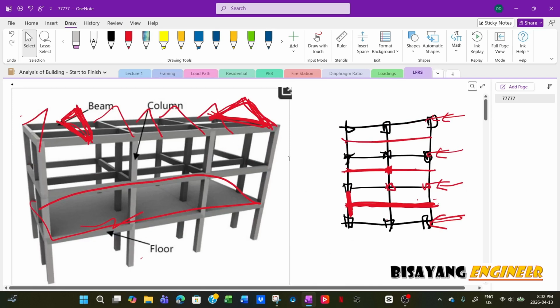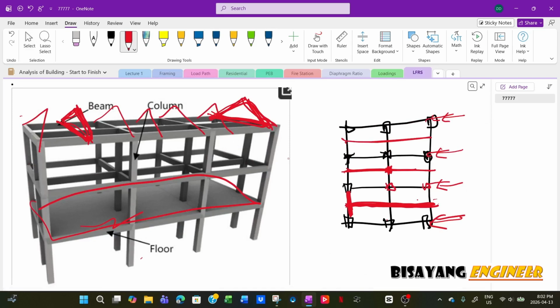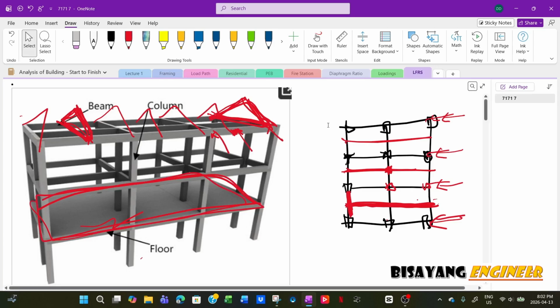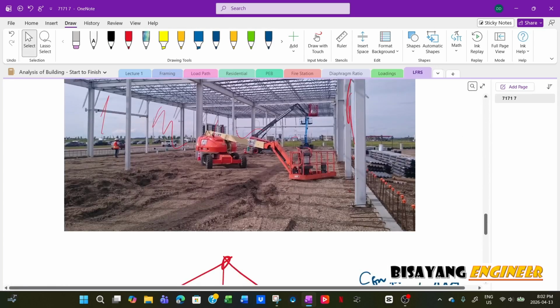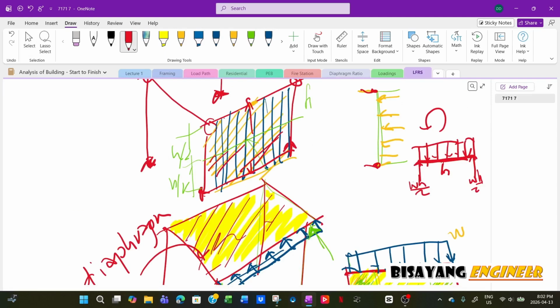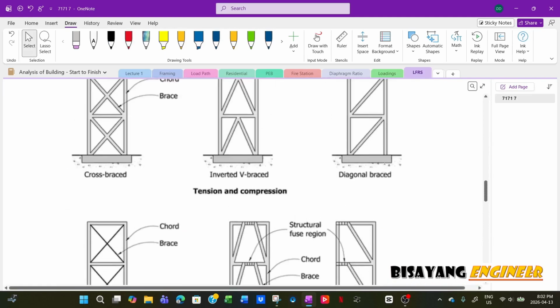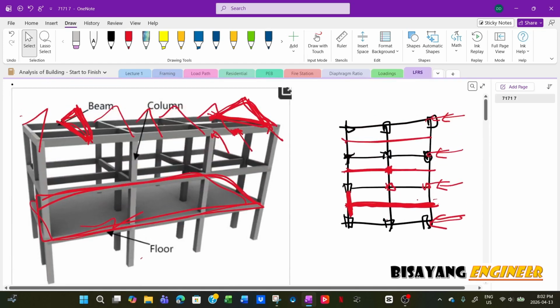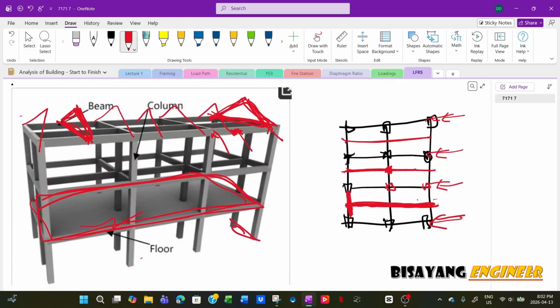And so again, you now have a concentrated load here, including at the midspan, where the beam has to bend horizontally. So that's another stress to consider when you design the roof beam. Now, if, like I said, you have a floor, then it will go to this one, like this analysis where you have a floor or roof diaphragm, then transferred to your beam columns, and then down to the foundation.